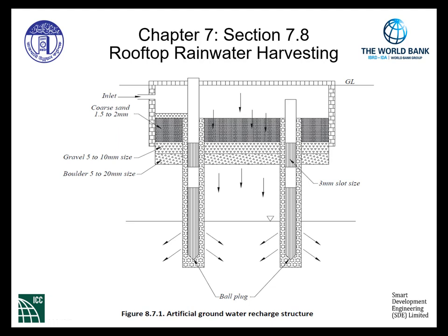Each rainwater seepage well shall have an inlet chamber with a silt trap to prevent any silt from finding its way into the subsoil water. The well should be terminated at least 5 meters above the natural static subsoil water at its highest level, so that the incoming flow passes through the natural ground condition and prevents contamination hazards. Again, no recharge structure or well shall be used for drawing water for any purpose.